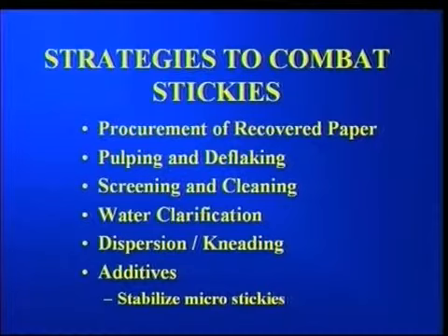The second strategy in combating the problem caused by stickies is pulping and deflaking. Here we want to do relatively gentle pulping at high consistency, preferably using a drum pulper or high consistency helical rotor pulper, because they degrade the stickies to the least extent. And subsequently large size stickies can be removed by the use of screens and cleaners.